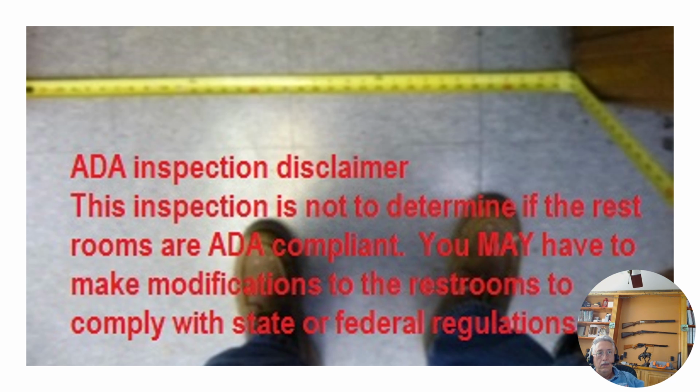Let's check a restroom, handicap restroom. It says doors 36 inches. ADA stands for Americans with Disabilities Act. So we put a disclaimer in our report that we're not there to do an ADA compliance inspection, but I will refer to it if I need to for whatever reason. You can download the ADA requirements for restrooms online in a PDF, and I recommend you go through them and take them with you when you do a commercial inspection, so you get everything memorized.